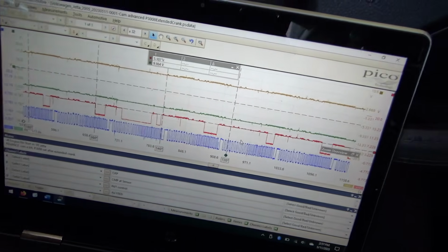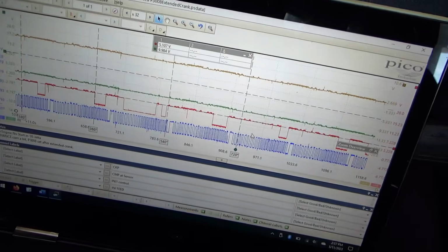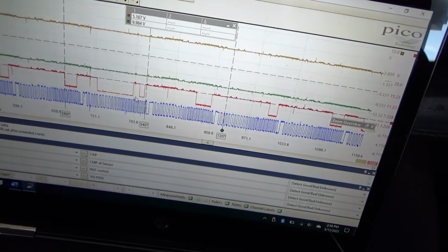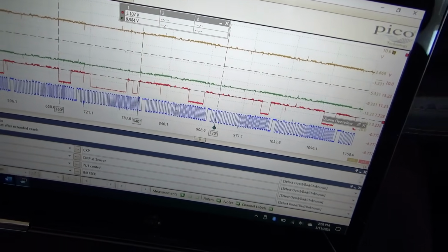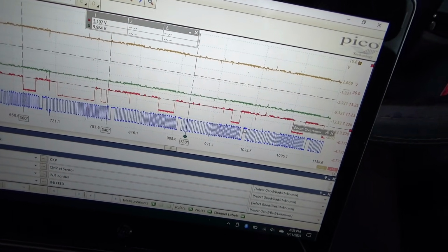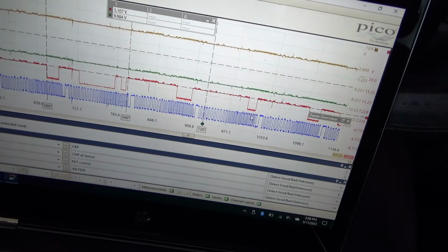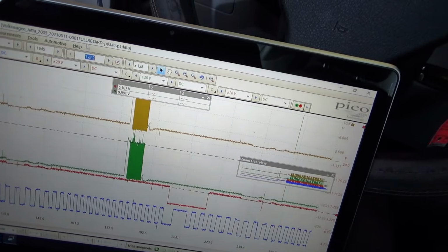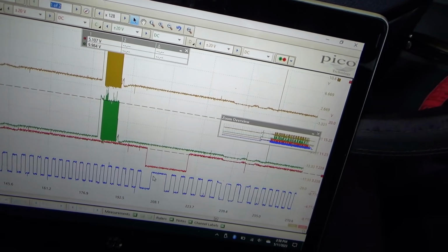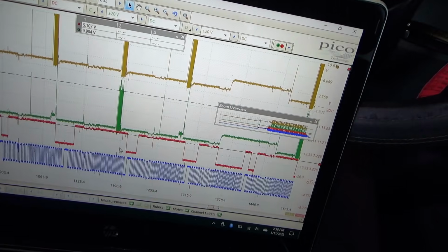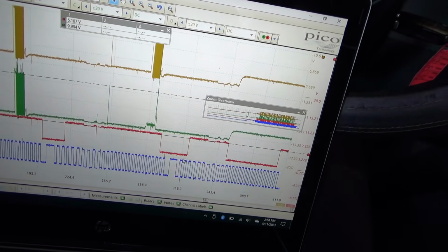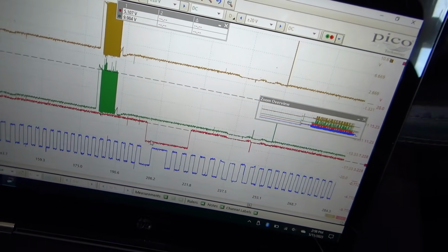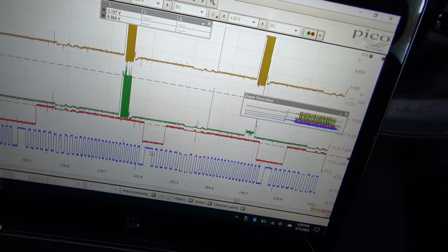Alright, so looking at these waveforms when we're retarding and advancing the camshaft. When we're advanced, we had no injector pulse and it said P3008. We're way off. These pulses are supposed to be right over the sync notches. This is full retard, and here we're pretty darn close, but you can see the cam is a little to the right, and this pulse isn't quite over the sync notch.